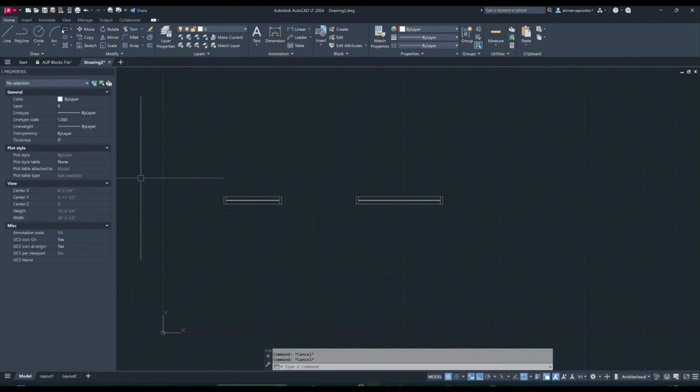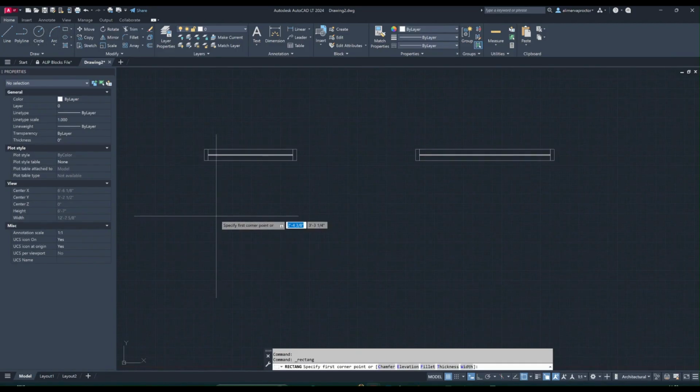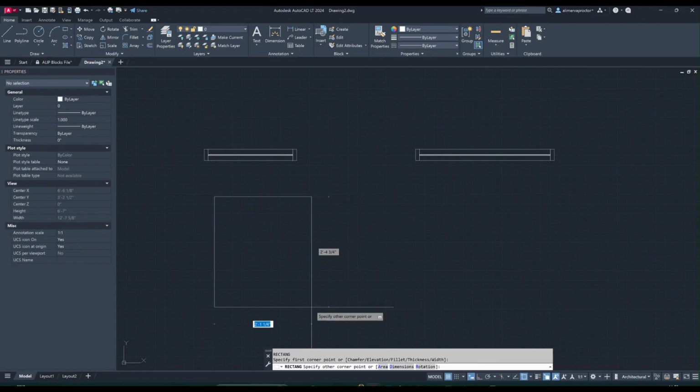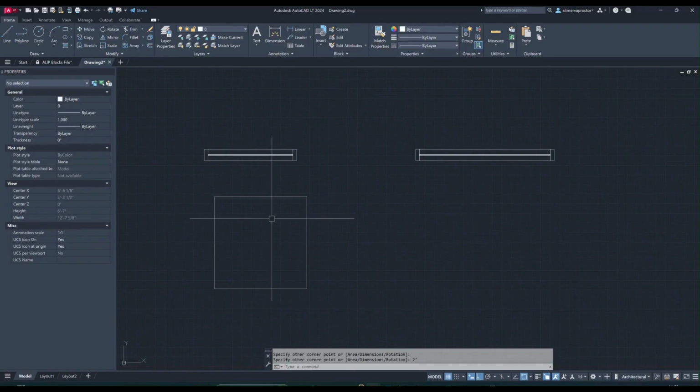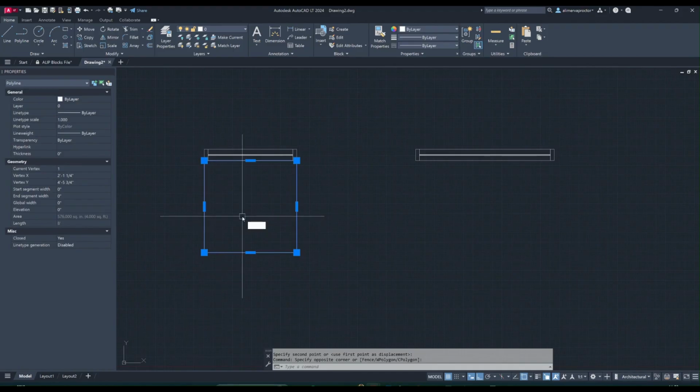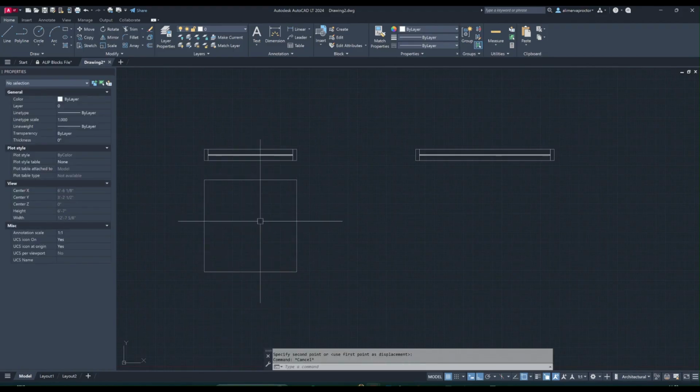So we're gonna have a rectangle again, REC, guys. Rectangle, so this will be 2 feet, tab, 2 feet, right? And if you want to line it up, you can touch the entire rectangle, move it, and just carry it right underneath that, tab it right there, and then move it down. You learn how to control those better later.